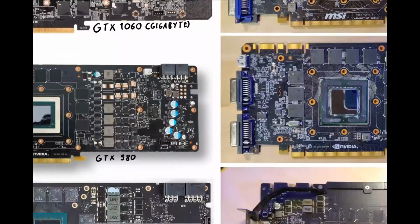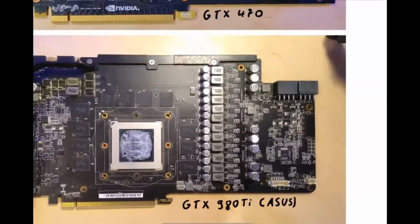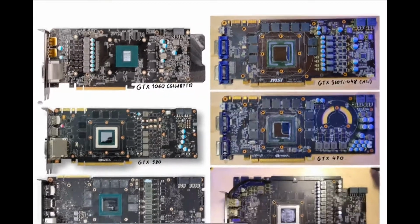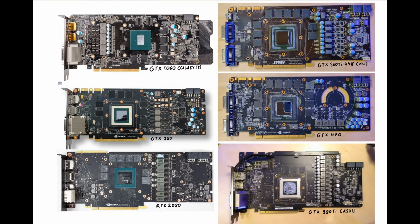And basically a more power hungry card will have an 8 pin, like this right here, the 980 Ti has 2 8 pins. And yeah, there's not that big of a difference between a 6 and an 8 pin. The 8 pin basically has one extra ground connection, and the other extra you add is a sense pin, so the card knows whether the 2 extra are plugged in or not.